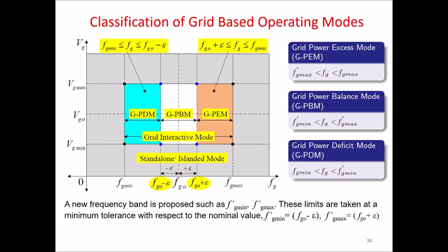When the microgrid is in standalone mode, there is no voltage source available from outside. There is no voltage reference, there is no grid connection. So it has to generate voltage to supply the load. And therefore, the microgrid inverter will act in a voltage control mode. This is a very important thing.